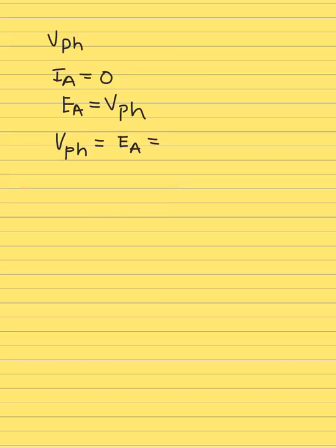In the previous step, we calculated the value of EA for a terminal voltage of 480 as 532. Since there's no change in the field current, the EA, the induced voltage, depends on the magnetic field in the rotor. So that's why EA will remain 532 volts. And now under the no-load condition, your terminal voltage will become equal to 532. So that was part D of the question.